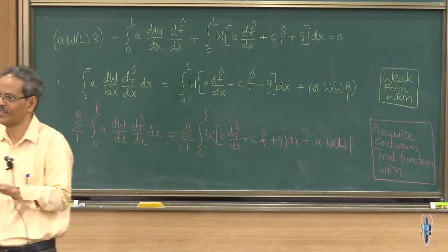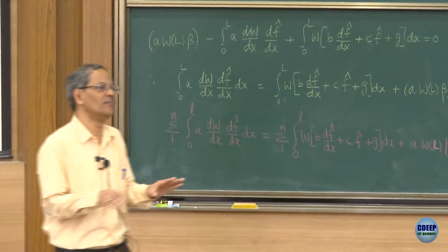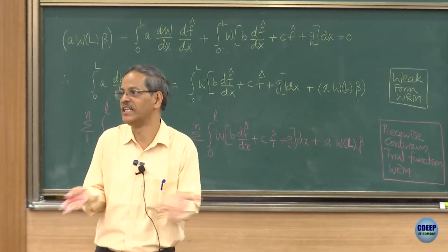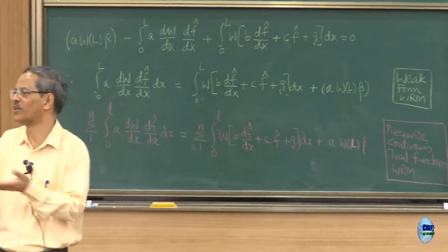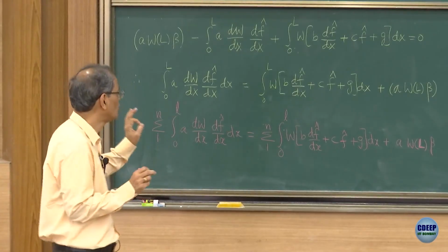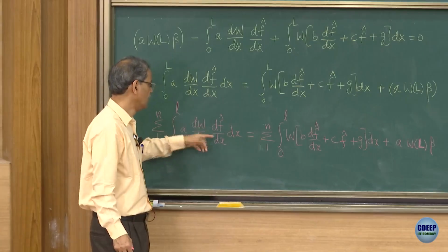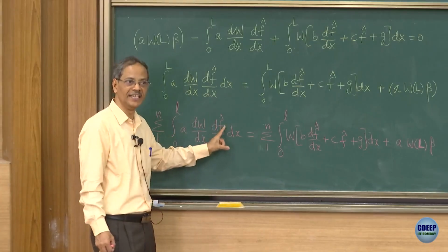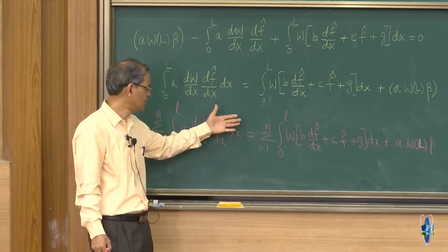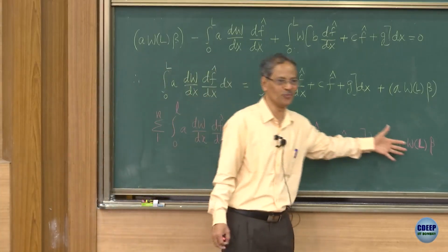Okay, so now we will define the element. The simplest element to be worked out is the linear element, with linear shape element functions, linear interpolation of the displacement or temperature or whatever variable you have. So, linear variation. I am going to formulate first using this equation, assuming that f hat would be linear. If f hat is linear, then w also will be linear. First derivatives will be constants. So that would be the simplest element that I can formulate.